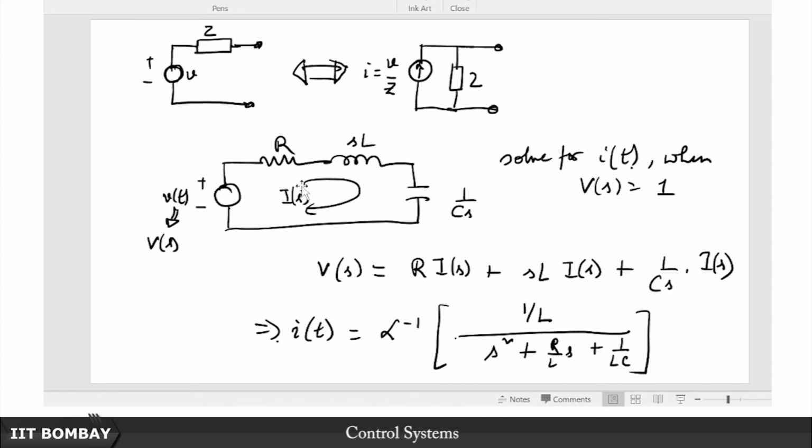I must warn you, however, that if you want to solve for the zero input conditions, then remember the Laplace transform method only works when all of your variables and their derivatives are given at the same instant of time, which is every or one of their values are specified at 0 minus, t is equal to 0 minus.